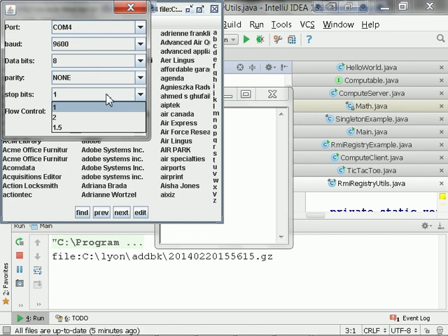And asynchronous signals need to have some sort of a bit clock on the receiver. And that bit clock synchronizes with what's called the framing bits as they come in through the wire. So the RS-232 receiver, which is also called a UART, or Universal Asynchronous Receiver Transmitter. That's usually a chip, although here in the new age they probably just have it on the motherboard. There's